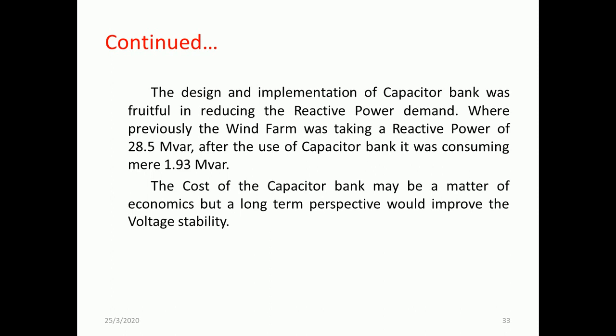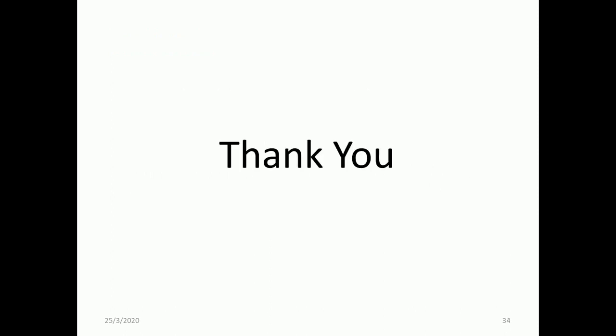The design and implementation of the capacitor bank was fruitful in reducing the reactive power demand. Previously the wind farm was taking reactive power of 28.5 MVAR. After the use of the capacitor bank, it was consuming merely 1.93. The cost of the capacitor bank and design is again a matter of economics, but from a long-term perspective with respect to voltage stability it is important. So that's it for now.